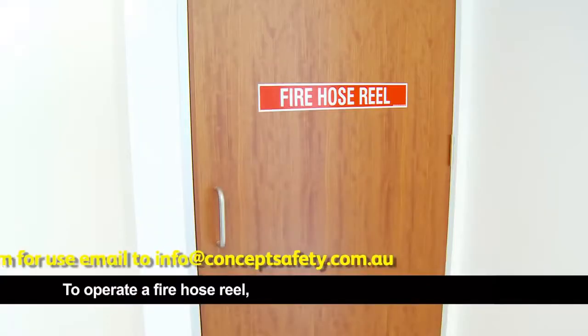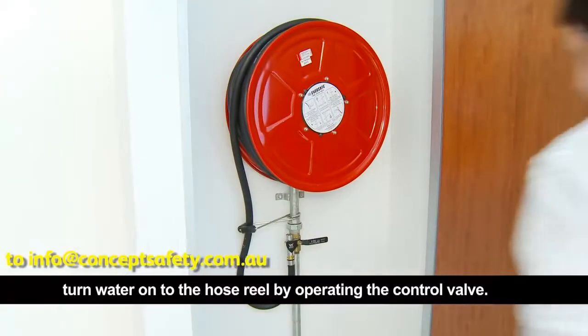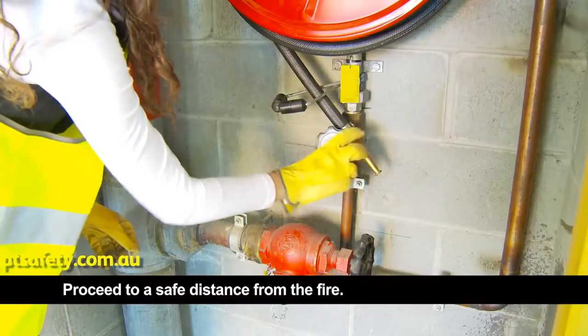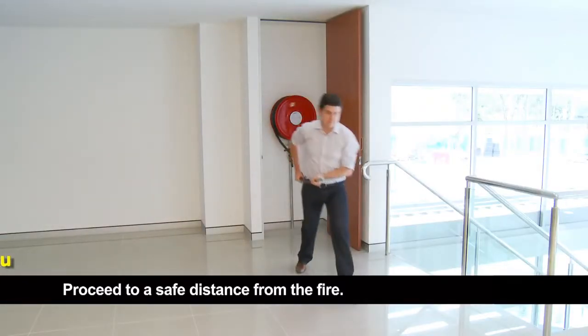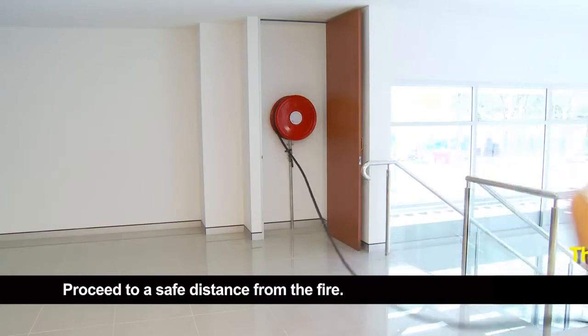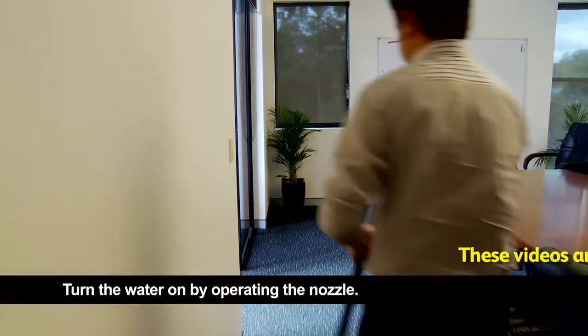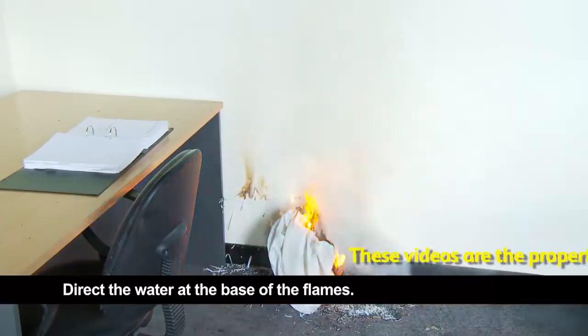To operate a fire hose reel, turn water onto the hose reel by operating the control valve. Remove the nozzle from its bracket. Proceed to a safe distance from the fire. Turn the water on by operating the nozzle. Direct the water at the base of the flames.